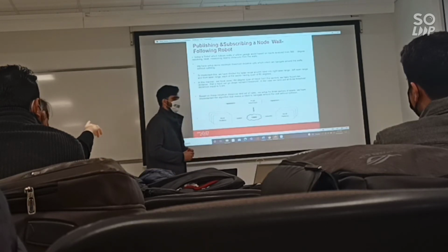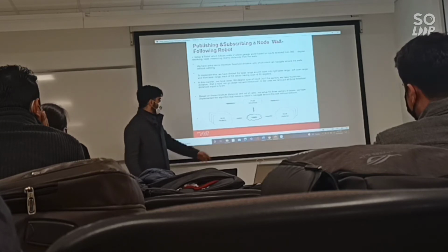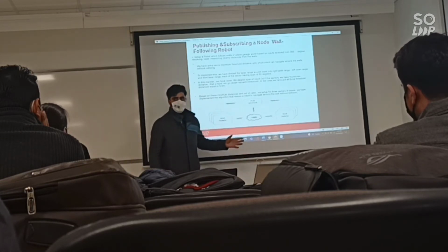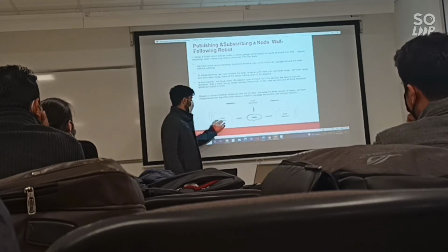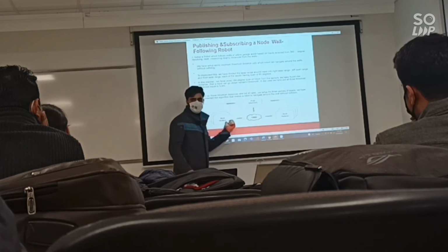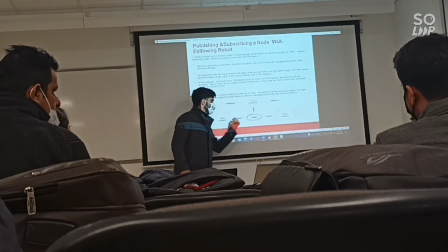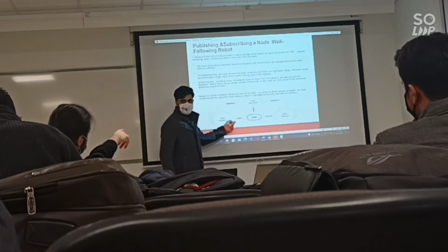First of all, how ROS works is there are different nodes. For example, I have written a node to follow the wall. There must be something else doing something different. So there is a thing called the ROS master. It should know everything that's happening in the system. Whenever you use ROS, if one node requires information from another node, they do not directly exchange their information.